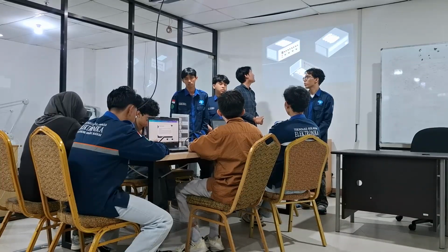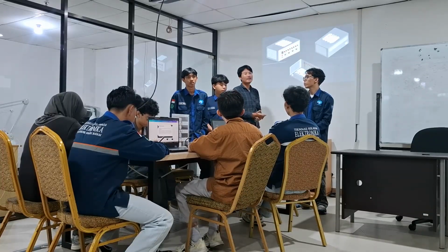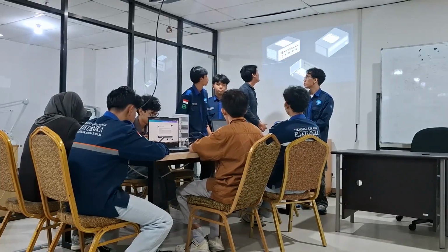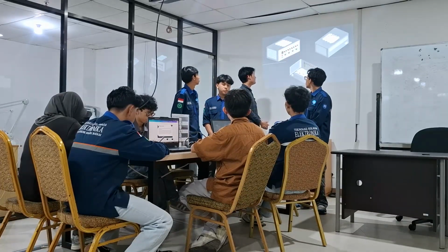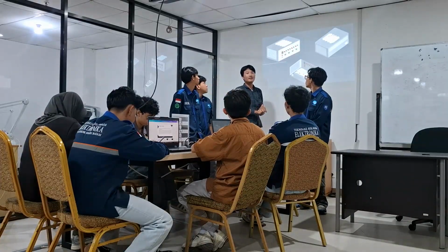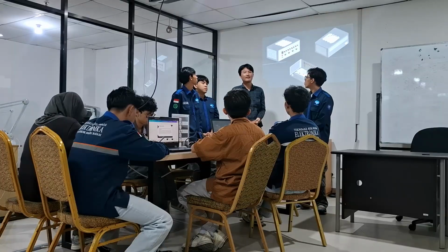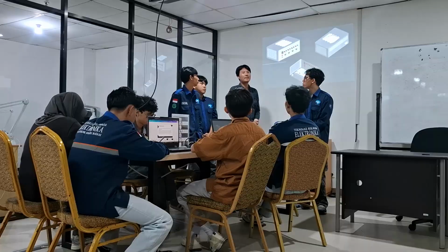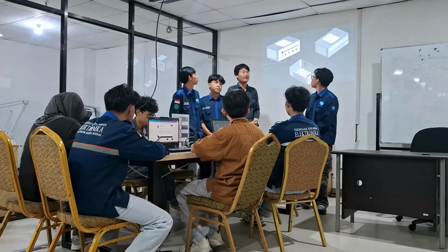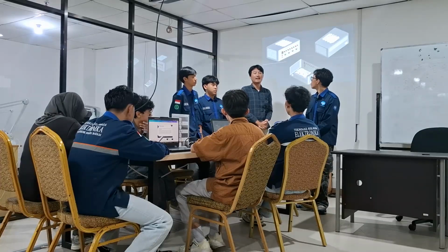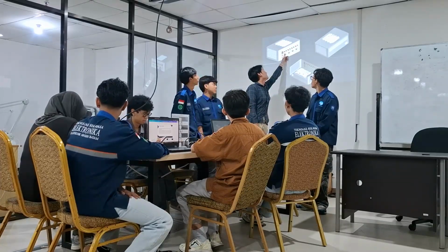The circuit protection is what detects the fault. For example, with short circuit protection, when channel 3 has a drastic increase in current, the protection circuit will cut off immediately and limit the current, and send a signal to the LED light to indicate the fault. I think that's all for me.